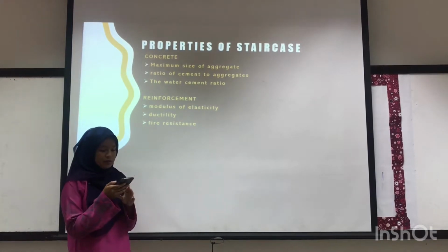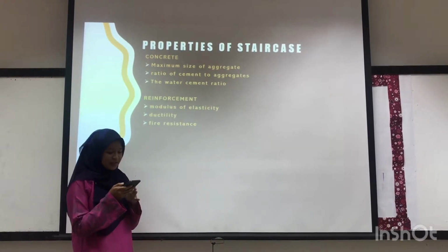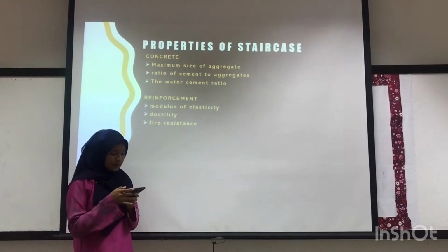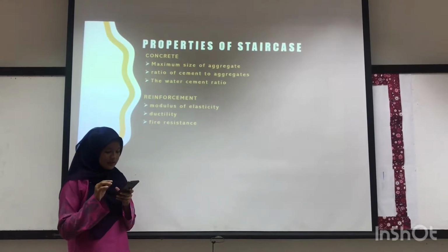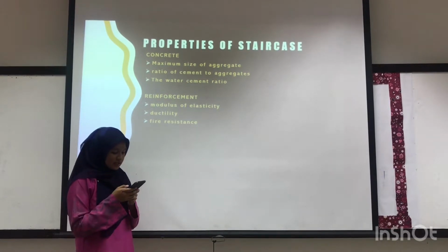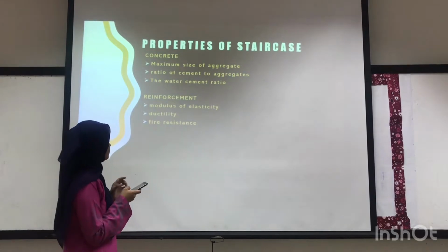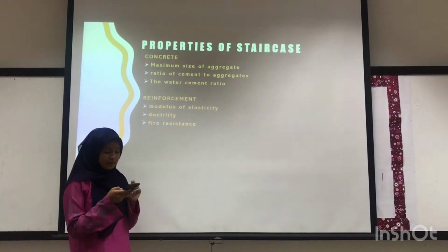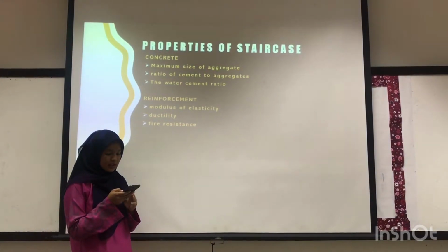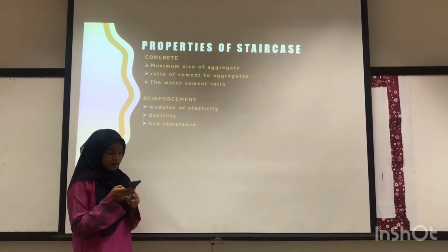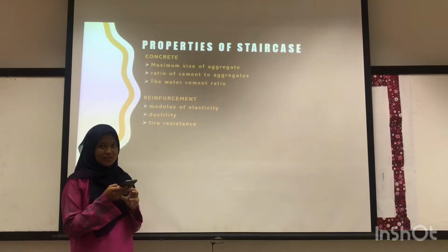The ratio of aggregate to sand to cement is an important factor in determining the compressive strength of the concrete mixture. A concrete mixture ratio of 1 part cement, 3 parts of sand and 3 parts aggregate will produce a concrete mixing of approximately 3000 psi.